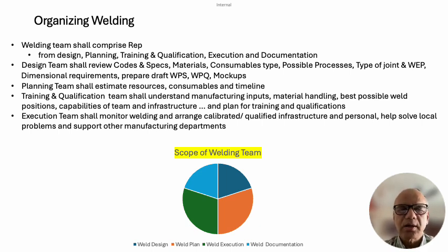our fabrication, like after 2 or 3 shells are welded, then we are going to have 2 circumferential seams, and at that stage, or for a dish end when we are going to have a long seam, before we form it, it may have a heat treatment requirement which is not specified by the customer, but that's a good engineering practice which we are incorporating to avoid locked-up stresses before we take it for the subsequent operations. So like that we are going to really work in the planning and finalize the consumable quantity, type, size, specifications, and superimposing requirements.